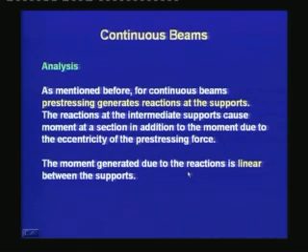The moment generated due to the reactions is linear between the supports. Since the reactions are point loads separated by a certain distance, the moment due to the reactions is a linear variation from one support to another support.